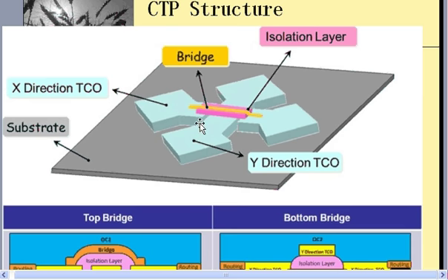And in order to make it, you can see, at the bottom there is one layer of electrode, and there is a bridge there. In another layer, we need to make a bridge, to make this into another layer. Otherwise, it will be separate and not conducting.